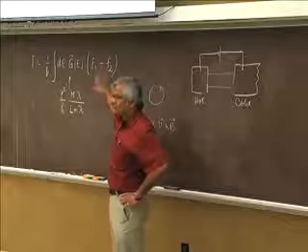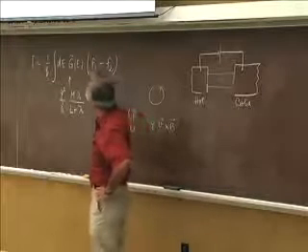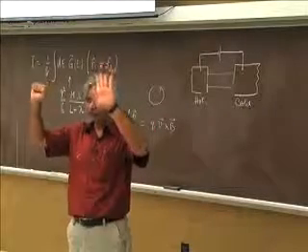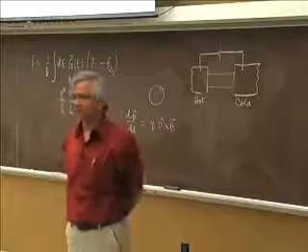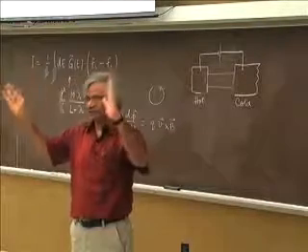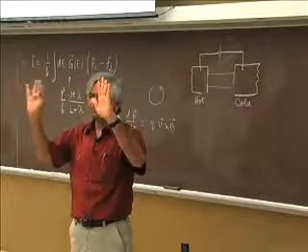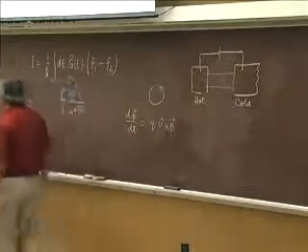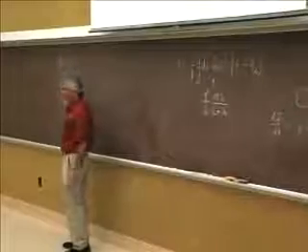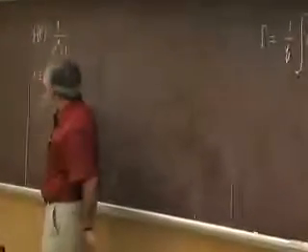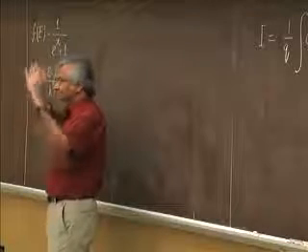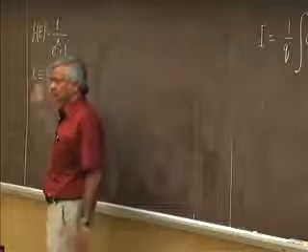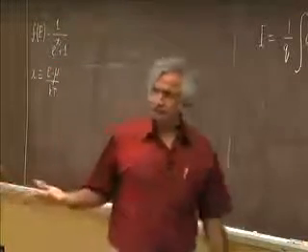That's all right here. The way we said it was the Fermi functions in the two contacts are different because you have applied a voltage. We had two different chemical potentials. But supposing we consider the situation when the chemical potential is the same, I have not applied any battery, any voltage across it, just the temperatures are different. Of course, that would make the Fermi functions different, because the Fermi function is E minus mu over kT. Usually the reason F1 is different from F2 is because mu1 is different from mu2. But let's say no voltages. All the mu's are the same. But that's fine. The F's are still different. There's a kT1 and a kT2. They're two different things.